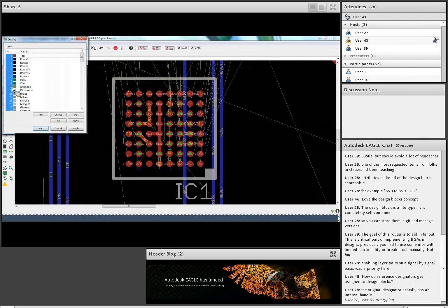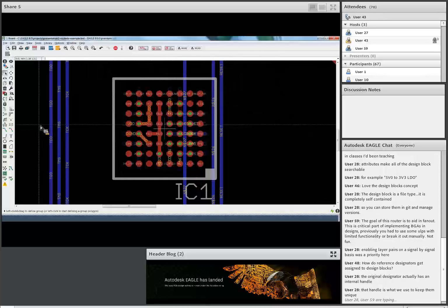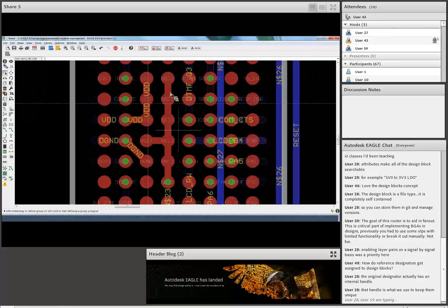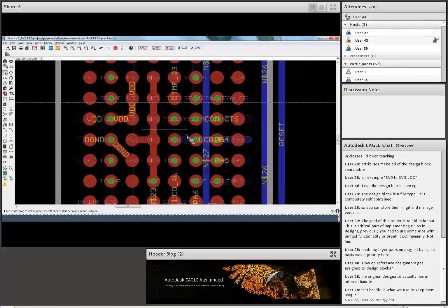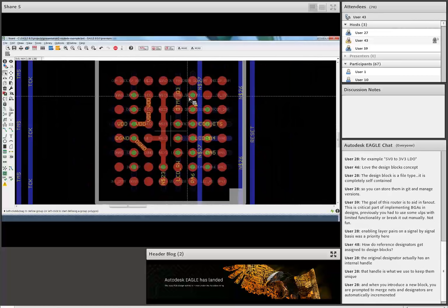Thank you very much. Click on routed. And here's our BGA fan out. It's already done. So for a simple component, and I gave it many layer options, it was able to finish pretty fast. So if you could see here are my BGA vias, my micro vias have been created. It's using multiple layers, and basically, in essence, what it did is that it did a fan out. In other words, it took all of the connections that were within the BGA itself, and it fanned it out.